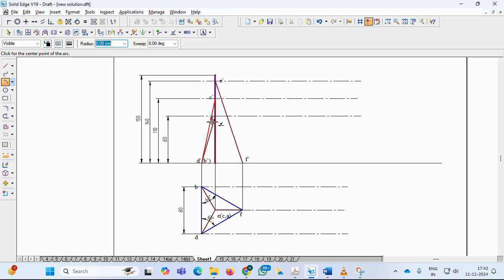So I want to find the true length of these wires, means true length of these lines. These are the apparent lines. So now I am going to rotate these lines and I will make it parallel, and then I will project on the top view. Sorry, from here.